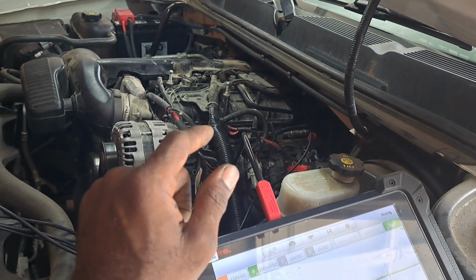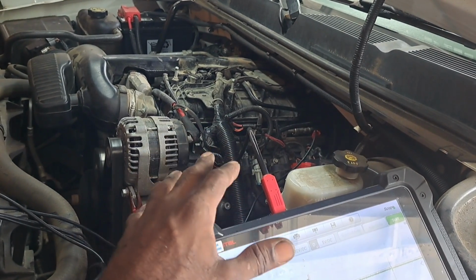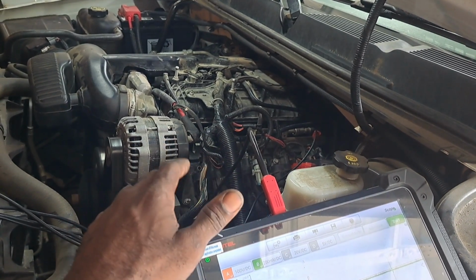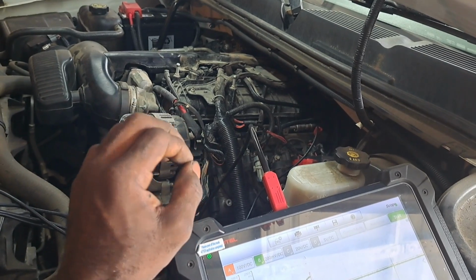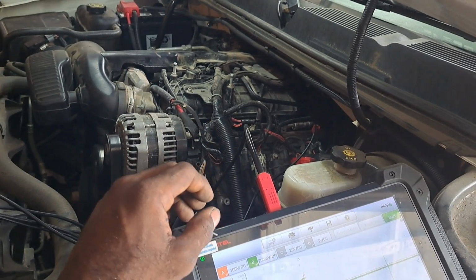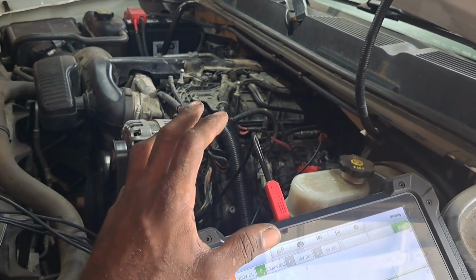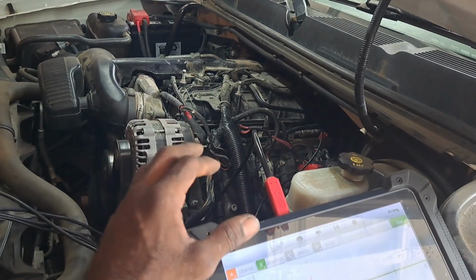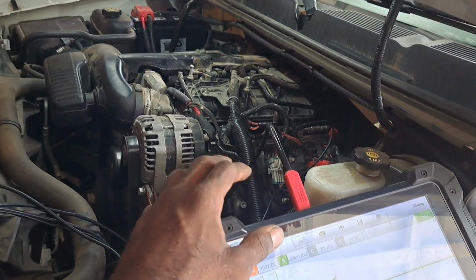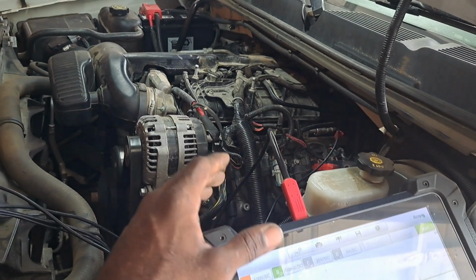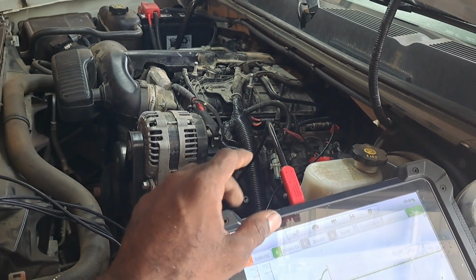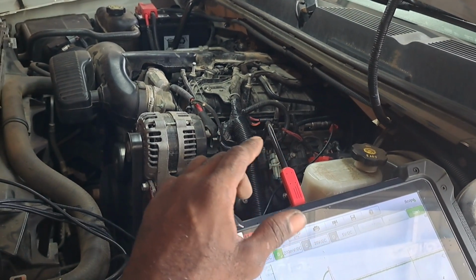So it got better when I did the tune-up with the plugs, but the last thing that needs to be done is those injectors, and it needs to have that particular spray pattern or atomization for proper combustion. I wish it was intelligent enough to tell us the cylinder, but it's just not. It's still old in comparison to newer vehicles.